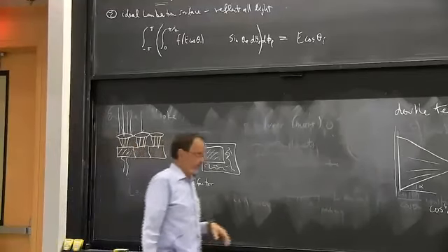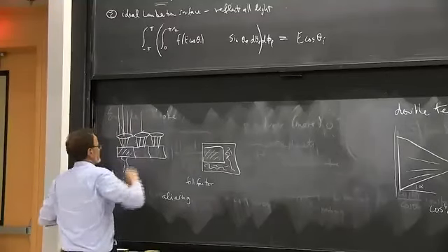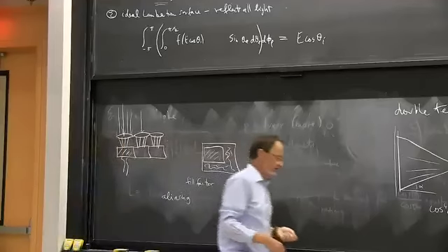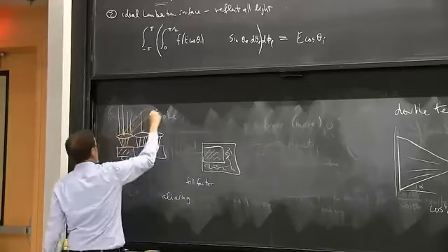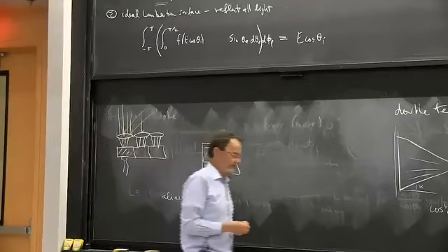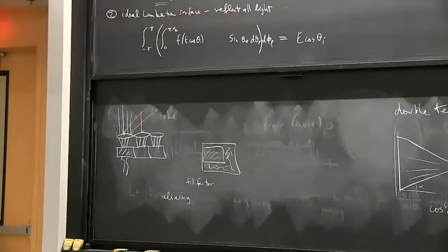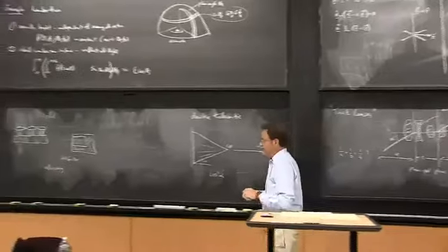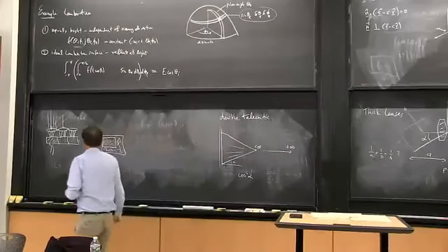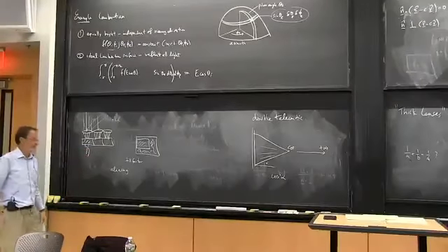Okay. Now, this works great if light is coming in more or less perpendicular to the surface. It's not so good if the light is coming in at an angle, right? Because then you'd have to somehow change the scale of the lenslet array, and even then you can't make it work correctly because there's a spread. The lens has areas that are in different directions. So anyway, to cut a long story short, there are several reasons why people like light to come in perpendicular to the sensor, starting with the cosine to the fourth.